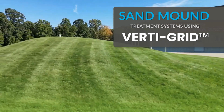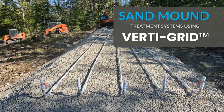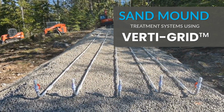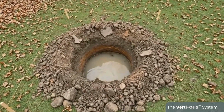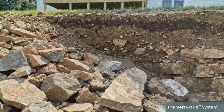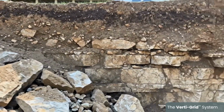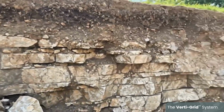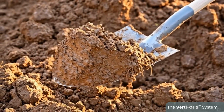In many parts of the country, sand mounds are being used to overcome natural site limitations for on-site wastewater systems. Sites that have seasonally saturated soils at a shallow depth, a shallow soil mantle over bedrock, or slowly permeable native soils are not compatible with normal methods of drainfield construction using below-the-surface excavations.